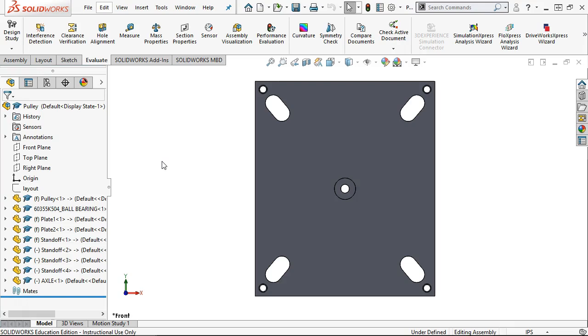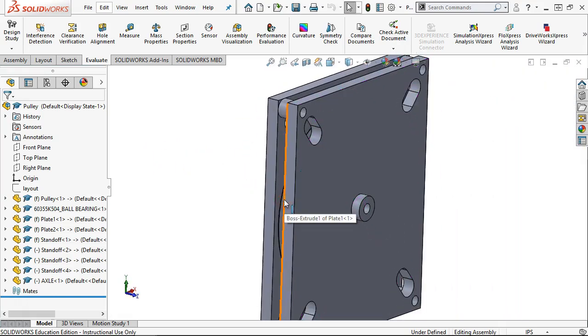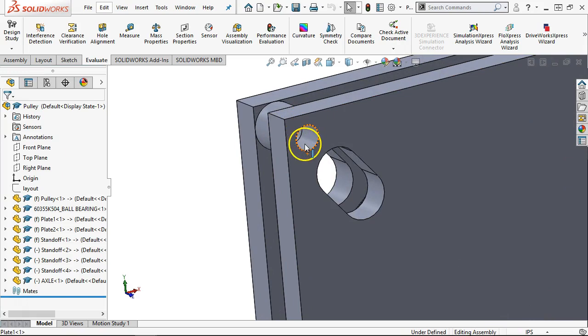What the virtual condition says is that our features that we're applying these tolerances to, at some point it comes down to a center line, or a midplane, that is a theoretical or virtual location. So when we shift over into maximum material condition and start applying those tolerances, we're looking at it in terms of that virtual center line, that virtual geometry that doesn't exist yet.